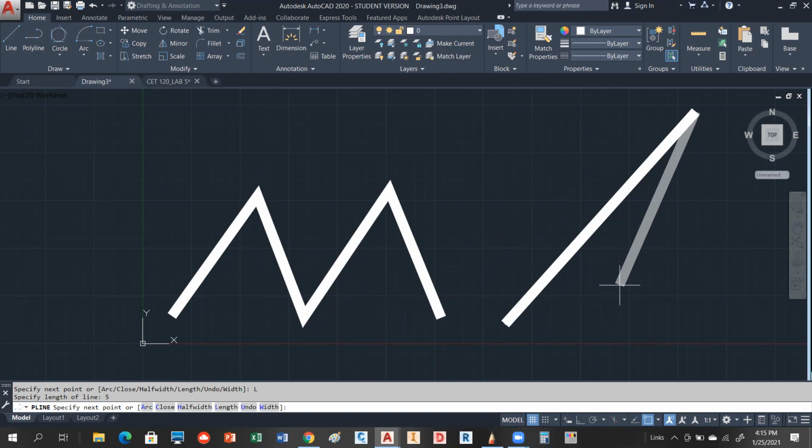So if you picked length and then you hit enter now, there's 2 possible scenarios. It took that end point and pushed it out units, or it actually tacked another segment on there. And if you click on this, you'll notice what it actually did. There was my second point, and when I told it to give it a length, it automatically just pushed that out. So this actually has 2 segments. So if I would explode this polyline, it's going to give me 2 segments back.